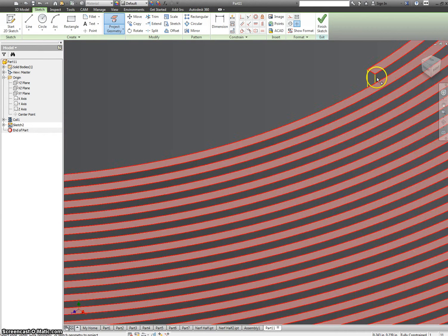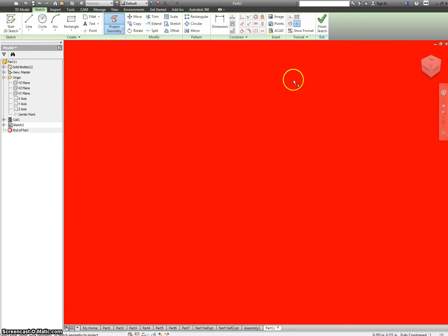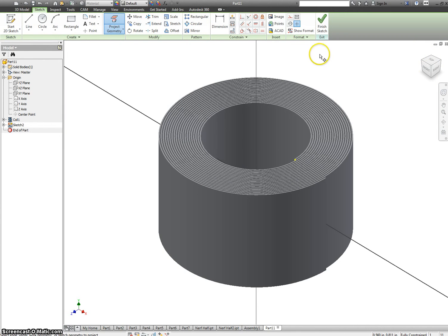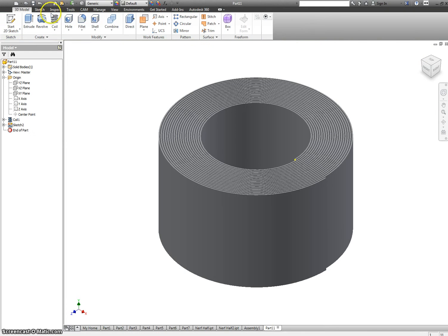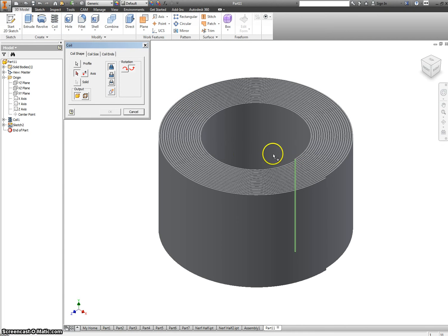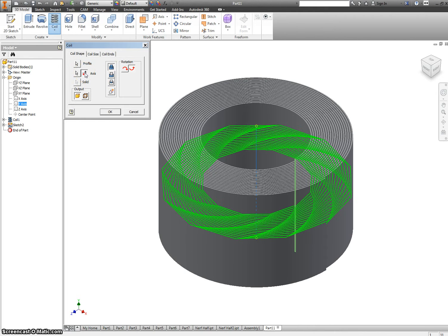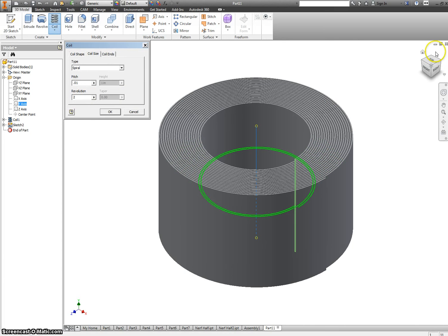Alright, I'm back. So you can kind of see I was able to get that to highlight, zoom back out again, and finish my sketch, go back to make another coil. That's my only sketch. I'm going to still use the y-axis, but this time I'm going to change the direction that it's going. Instead of 20, I'm going to say 2.